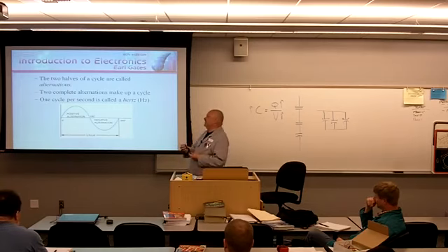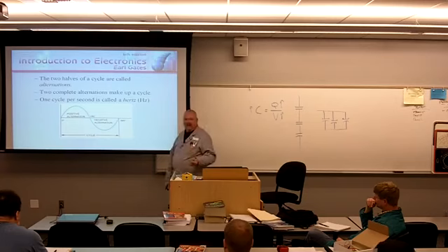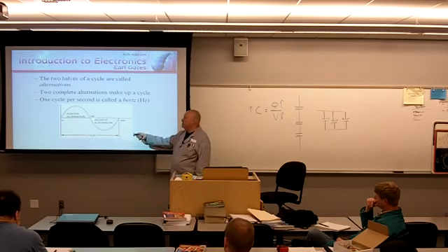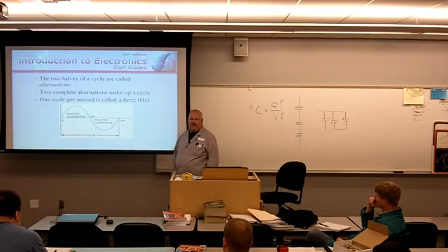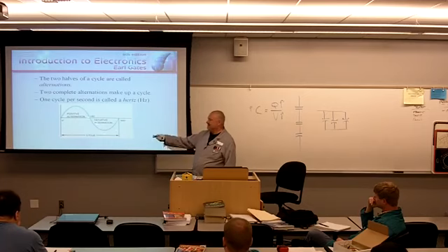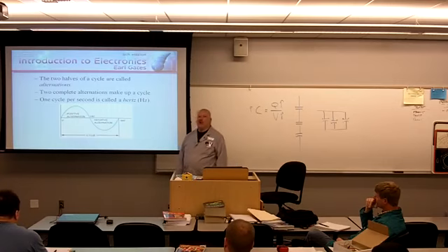We see here these cycles, and remember these degrees here are associated with the degrees of rotation of the armature through the magnetic field. It's that simple. When you rotate it 180 degrees through, you go from 0 to a maximum at 90. Now you're back to 0. So you've put it under the strongest influence in this first 180 degrees of the magnetic field. Then on the back side, you're putting it under a negative influence of that same magnetic field. You're cutting the lines of flux. Remember Lenz's law? Left-hand rule.